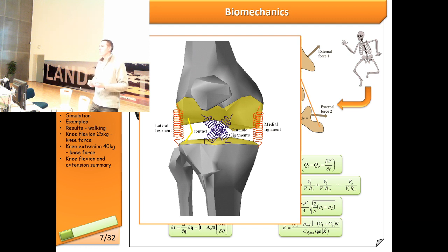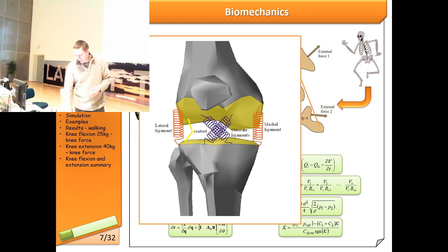If you have a more accurate model, first of all, it's more difficult to make this model stable, because it's very easy to draw something, but it's more difficult to keep it in place and make it behave as it should. And secondly, when there are lots of additional points to evaluate and lots of contacts, then your model will start to be slower. And depending on whether you want to do one simulation and you're happy, or you need to do a lot of iterations and you want to do some sort of optimization, it might put some constraints on where you can run it, whether one computer is enough, or you need to use a cluster, or you need a supercomputer for a very complex model.